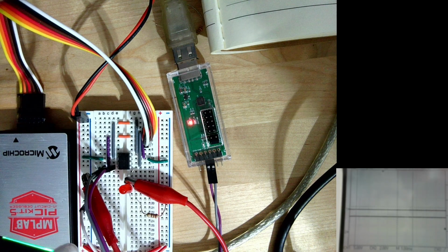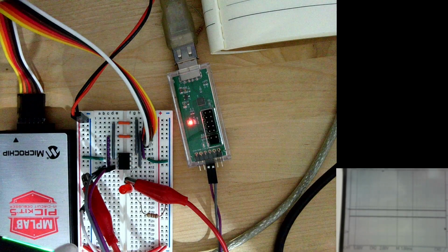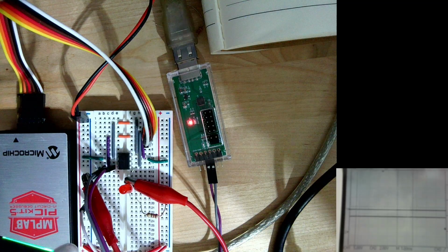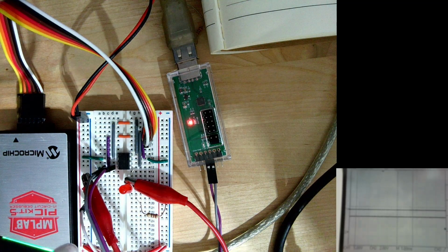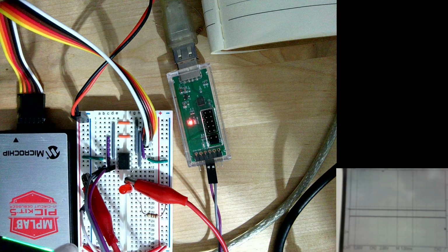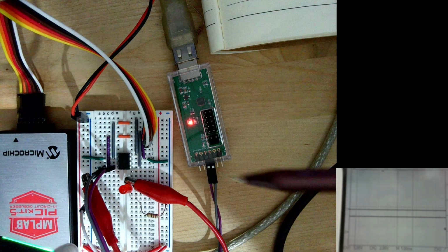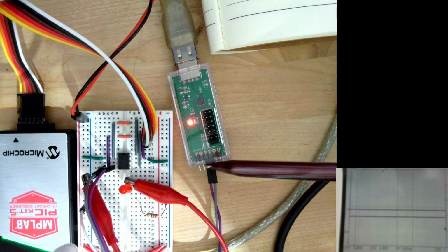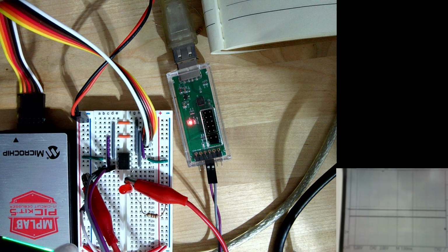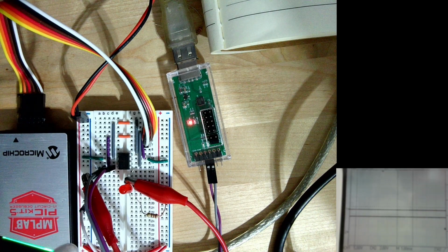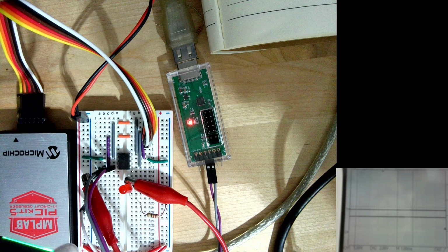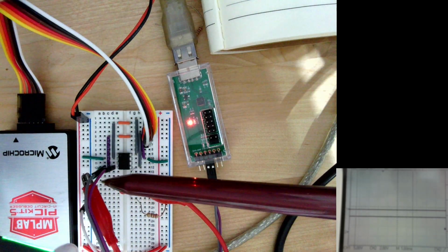There are other UART devices as well, so hopefully whichever one you have will work for this purpose. One thing you can do to check is jumper these across, open up PuTTY or some other terminal that can write to the COM port, and see if you get a return of whatever you type in. That's what's going on here.